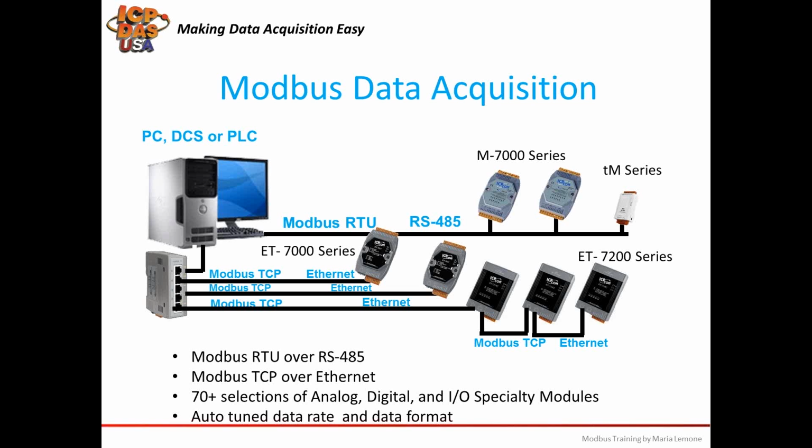Modbus TCP protocol is a variant of Modbus RTU protocol. It was developed in 1999 to allow Internet and Ethernet access of Modbus devices. Modbus TCP-based equipment communicates over Ethernet cabling. Many buildings have Ethernet cabling pre-installed, so adding Modbus TCP devices is convenient in many applications. Modbus TCP and Ethernet cabling supports communication distances up to 100 meters or 328 feet. Additional distances can be achieved if you add Ethernet switches like NS205.